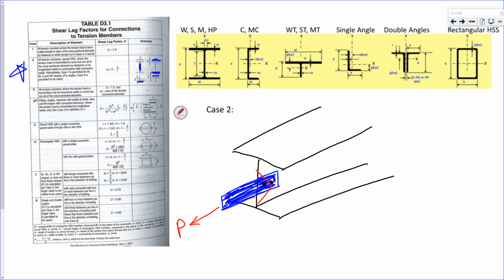You know, if you think about pulling that little middle of the web of my I-beam, you're pulling on that, and the rest of it, the 2 flanges, and maybe even parts of the web, might not be fully engaged. So you can't count on the entire cross-section when you're calculating your net area for rupture, right?